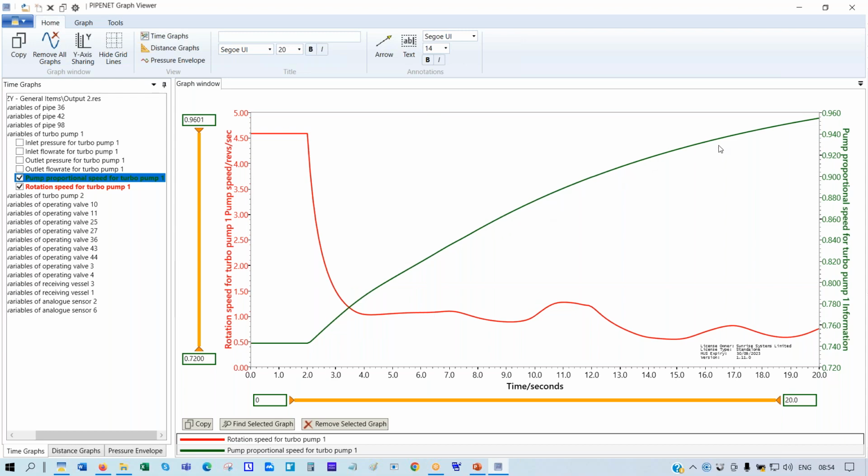The pump speeds up, or the control system tells the pump to speed up because the pressure is going down. The poor pump responds by saying, hey, I'm so sorry, I've got no power. You can ask me to speed up, but I cannot do that. I've got to spin down and either stop or just be ticking over. It depends on the pressures. Okay, so that is what we're doing.